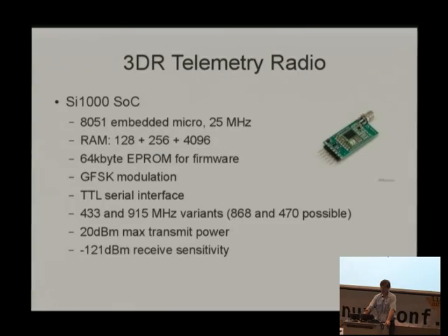And then there's second level paged memory at 256 bytes, and then there's a third level of secondary page memory, which is 4 kilobytes. Gosh, lots of memory. We have 7 bytes of that left for the final features. So at the moment we're down to 7 bytes of remaining memory on this system. So we're really pushing this chip to its limits.